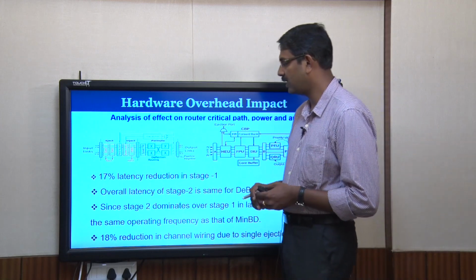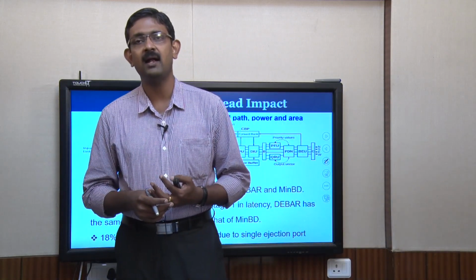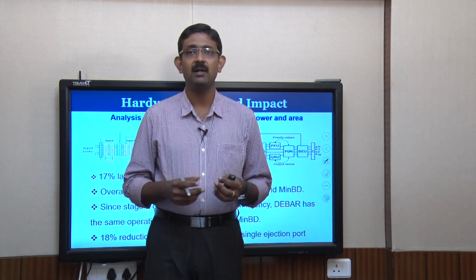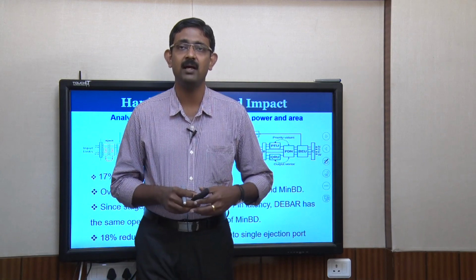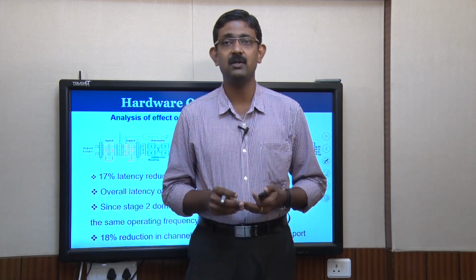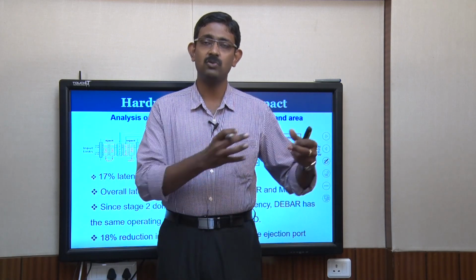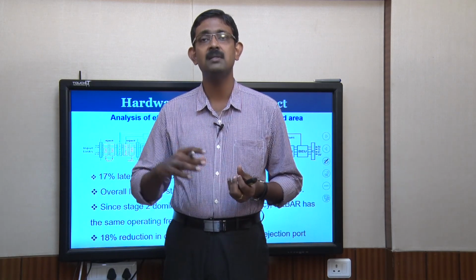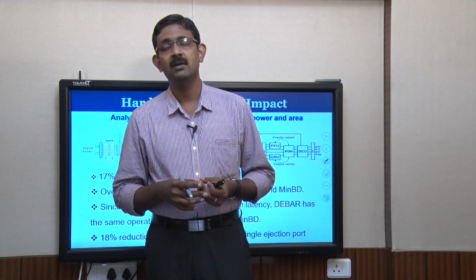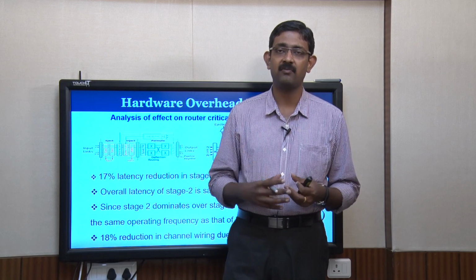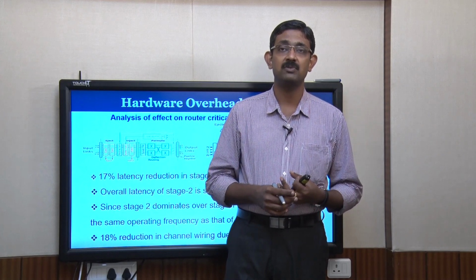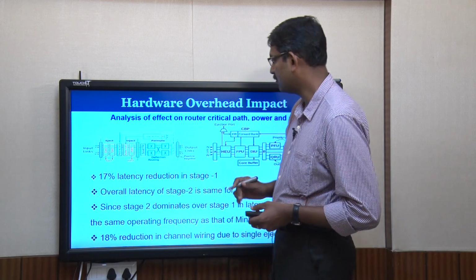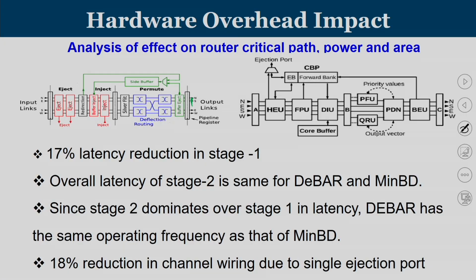Now, coming to the hardware overhead. Once you have a design in hand, computer architects normally try to describe this hardware in a hardware description language like VHDL and Verilog. Once you model your microarchitectural feature using this hardware description language, then we are going to synthesize them using the appropriate EDA tools and find out the synthesis report in terms of area and power consumption. So, both MinBD and D-bar routers were implemented in Verilog,